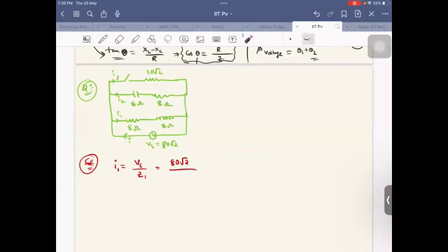And Z1, what is Z1, sir? Z1 can be written as a complex number: Z1 equals 8 plus j8. And Z2 can be written as 8 minus j8. That's it. If I want the magnitude of Z1, what is it from here? 8 root 2. Right? The complex number magnitude is 8 root 2. So done.